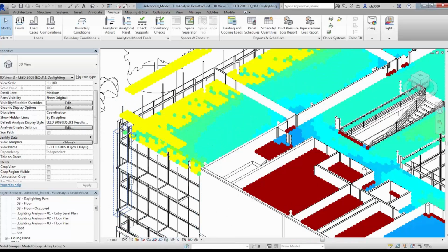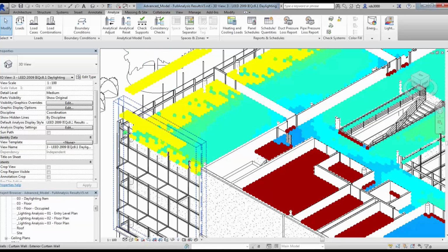So you can see that now you can actually see the grid of points. It's very dense. My point objects are actually a little bit too large to be able to distinguish between the points. But you can see here there are 5 points in this first 5 feet of the wall. So if I generate a high resolution analysis, a high resolution is a point every 1 foot. A low resolution is a point every 6 feet. So you're just not going to get as good a resolution.